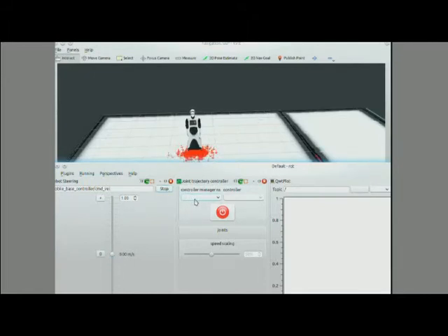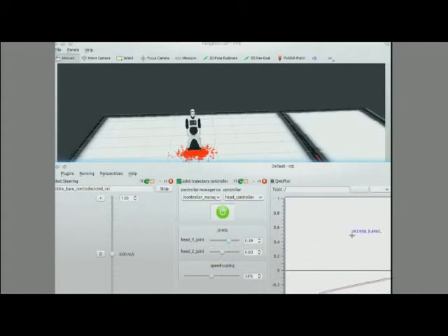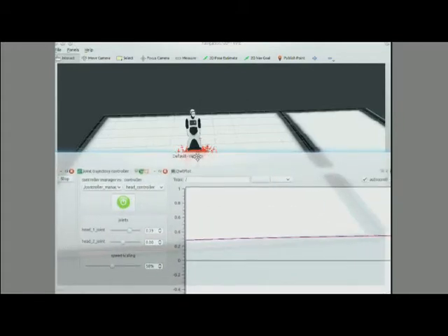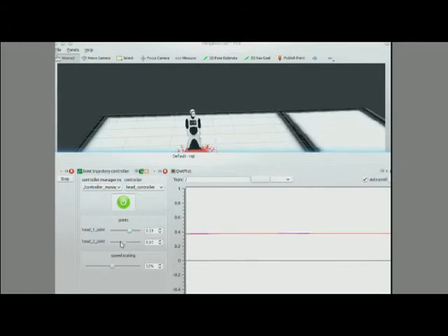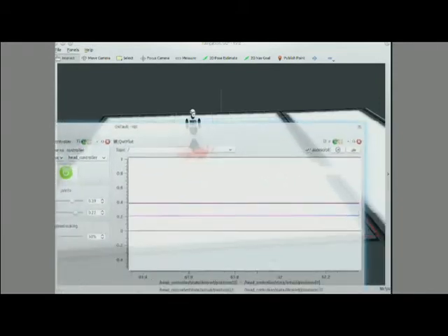Then this is from the ROS Control project. This is for the joint trajectory controller. You choose a controller manager, and then you choose one of the available controllers, and then you can simply move the joints. Can you see the head moving? Oh, and this is RQt plot, so you can also see the evolution of the trajectories. So this is really cool. So here what we're doing is basically talking directly to the controllers with a very convenient interface.